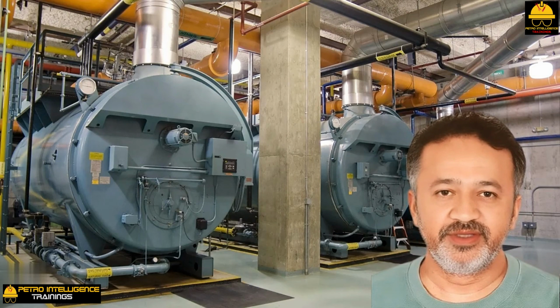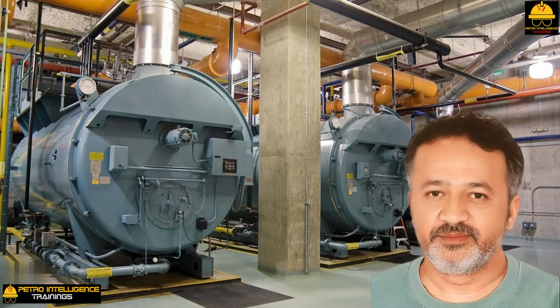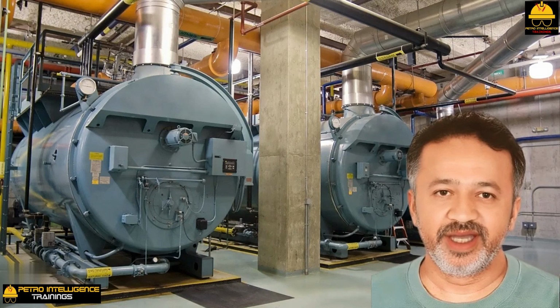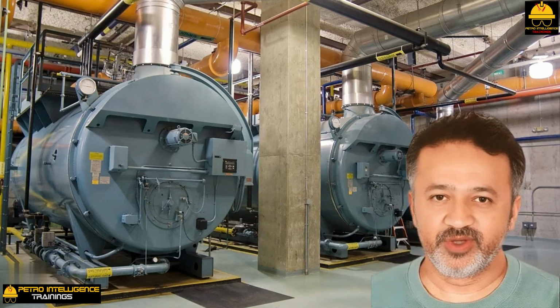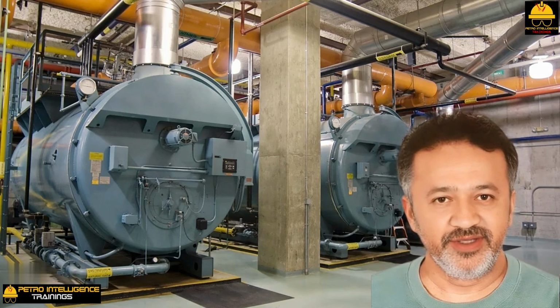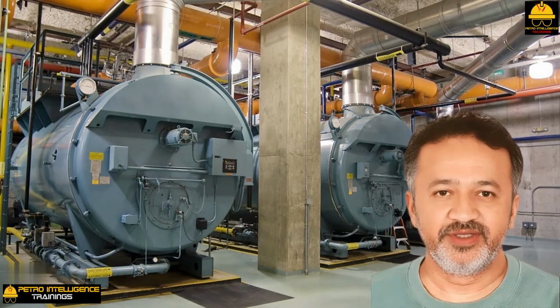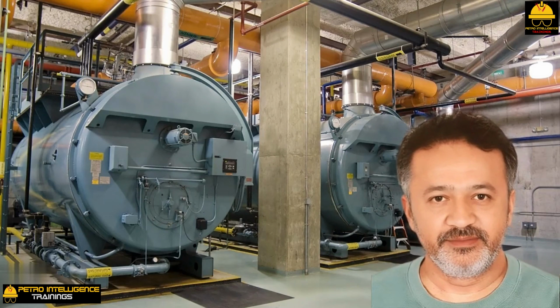If low sulfur, less than 100 ppm H2S, is being fired, H2SO4 corrosion should not be a problem. For boilers firing fuel oil, bunker, it's best to preheat the BFW externally to perhaps 350 degrees Fahrenheit to protect the boiler's economizer convective tubes from corrosion. If a small amount of vaporization occurs in the preheat exchanger, this should not compromise the operation of the economizer, provided that there is only a single inlet to the economizer section.